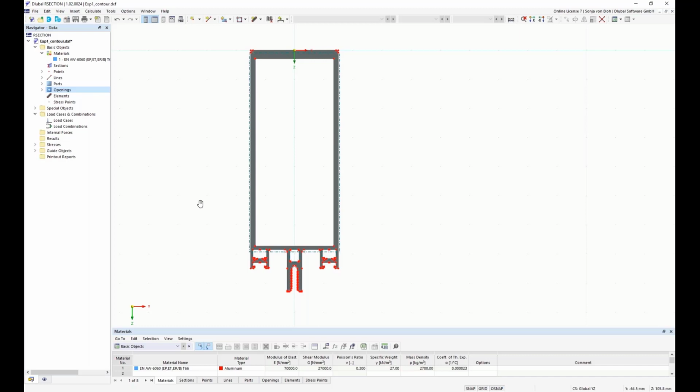The definition is also necessary for the calculation with the analysis method thin-walled analysis. Based on the elements, some cross-section values such as torsional moment of inertia and warping resistance are calculated if the analysis method analysis of thin-walled structures is selected. If the finite element analysis is set, the gross cross-section values are calculated using the FE method.